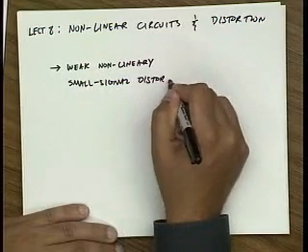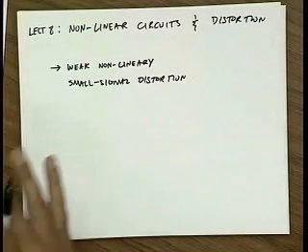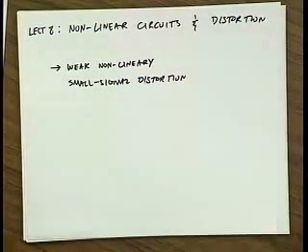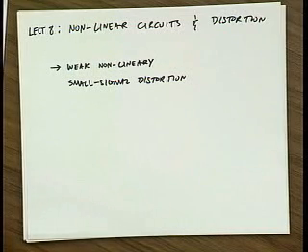distortion. So the idea is that we're driving the amplifiers with relatively small signals, and we're looking at the distortion products, which up to now for linear circuits we completely ignored, but now we see that there's going to be some small amount of distortion. When there's gross distortion, the power series analysis that we do actually doesn't apply. What this power series analysis lets us do is predict at least when the distortion is going to be so gross that it's going to require more sophisticated analysis.